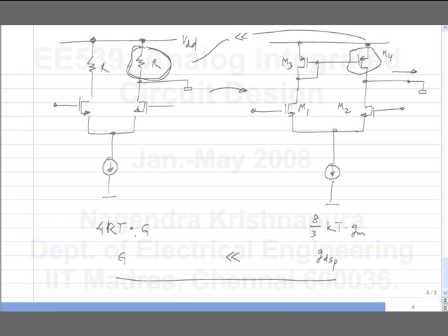Okay. I have this backwards, right? The impedance contributed by the active load is much higher. So the conductance contributed by the active load is much lower than that of the resistor. But its noise is not proportional to that impedance. Okay, I mean that conductance. It is proportional to something else. Here, if you have a conductance G, the noise is proportional to G. But in an active load, you get a certain conductance. The noise is proportional to the GM of that transistor, not GDS. Okay, so you get much higher noise.